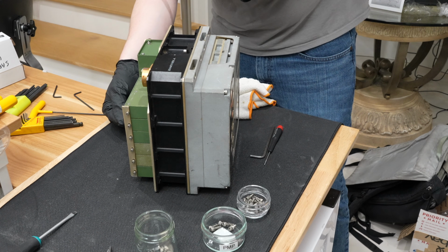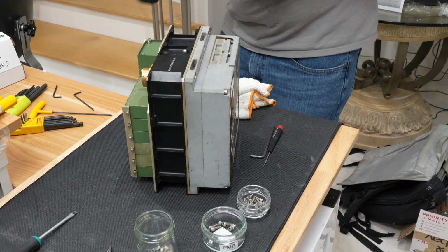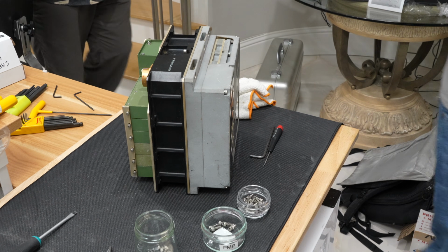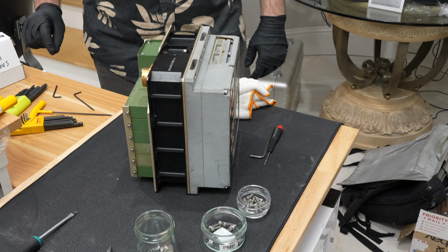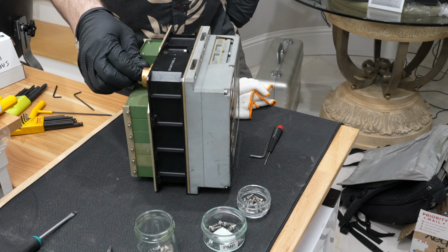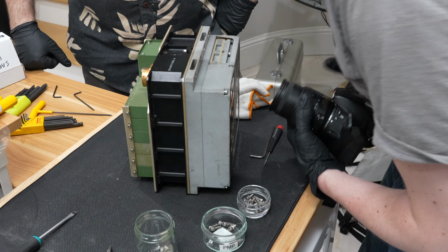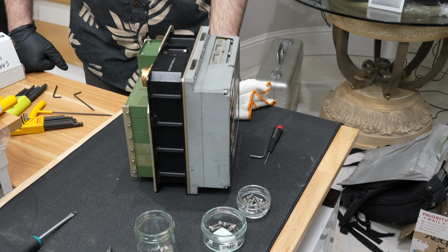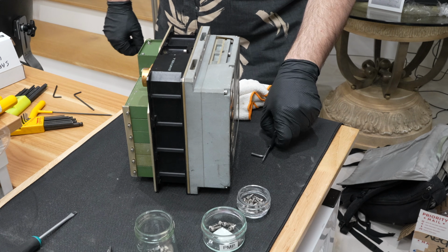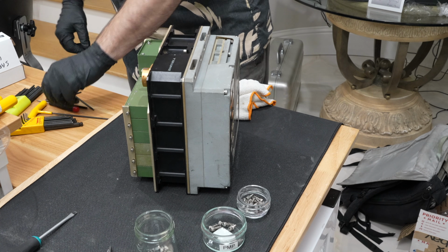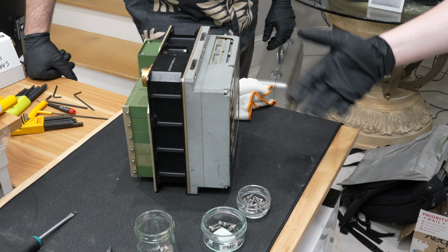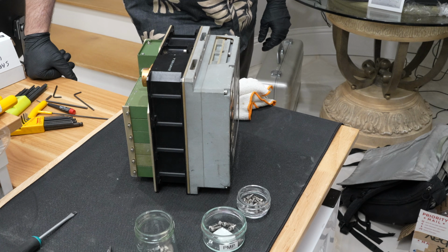Yeah, I have to imagine that this means that there's a battery relay on that one. A yellow dot next to the part number means that the thing is non-flyable for some reason. But they had so many problems with the relays and well, really throughout the program, not even just in the early ones. Apollo 12, twice I think during the launch countdown, they had a relay short in the DSKY that just caused the EL panel to fully light up and display all 8s.